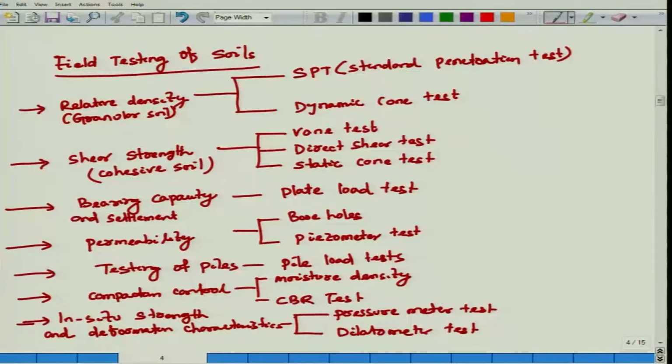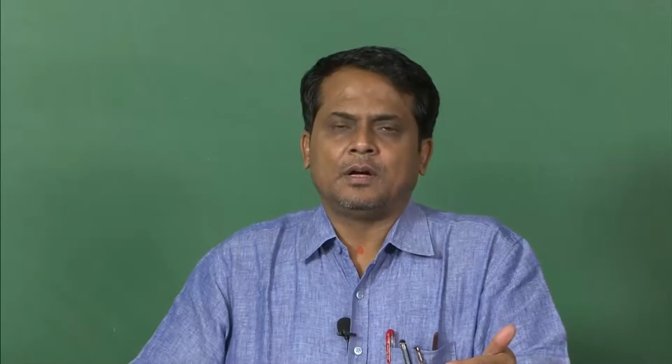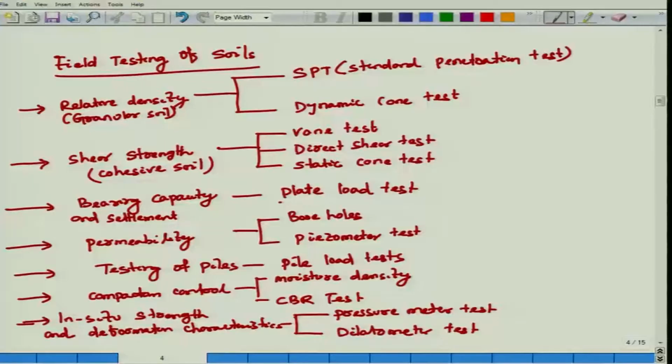Now, bearing capacity and settlement, in situ bearing capacity and settlement. If somebody asks, there is a ground, I am going to construct a building and below 2 meter I want to lay my foundation, so what is the bearing capacity of the soil below 2 meter? In that case you have to go for plate load test, plate bearing test. Every test has merits and demerits, we will discuss in brief.